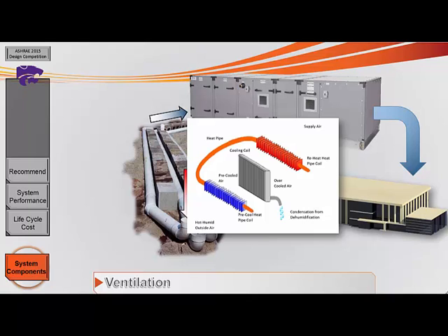required heating and cooling. First, the hot, humid air passes over the cool refrigerant, which removes the heat from the outside air prior to the cooling coil. After the air passes over the cooling coil, which overcools the air to achieve the desired dehumidification, it passes over the hot refrigerant, heating the air up to the desired temperature to be supplied to the room. The addition of heat to the refrigerant causes it to flow around the cooling coil due to the difference in temperature inside the horseshoe.